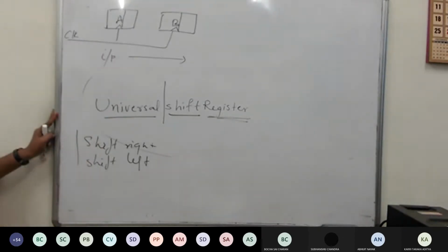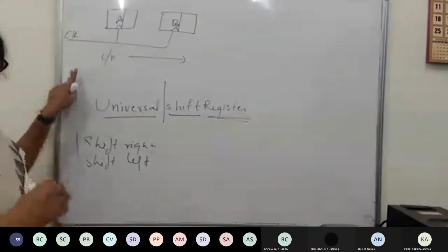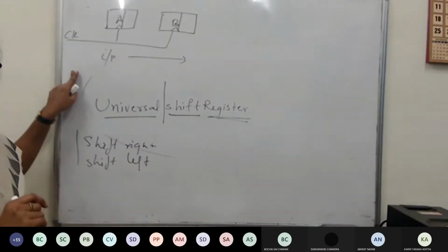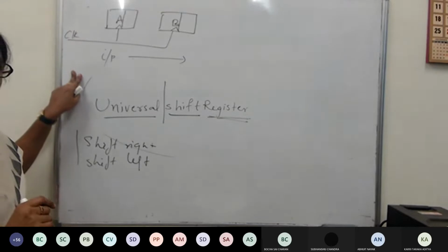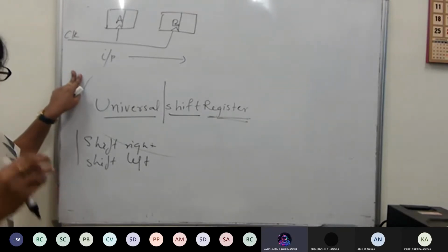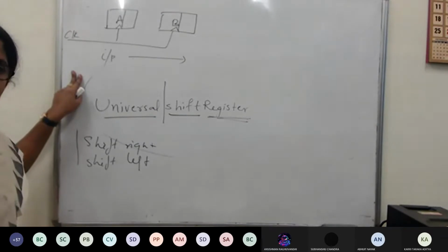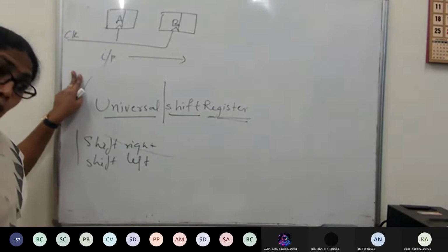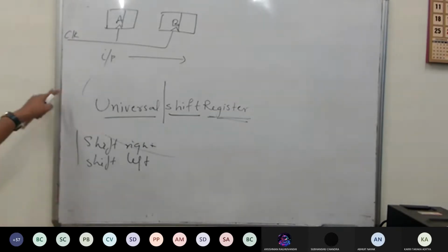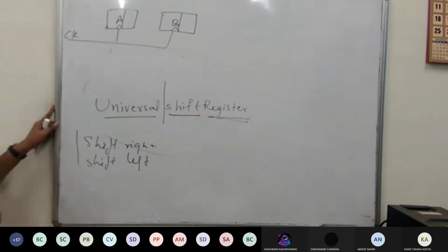Anyway, I'll give the solution itself. Can I use a multiplexer which can control this? Yes, ma'am, a 2x1 mux. Yes, we can use the multiplexer. Why? Because when I was delivering, I was trying to tell controlling. That control can come only from a multiplexer. And I'm giving the clue that we can use combinational circuits, so a multiplexer is best suited for that.